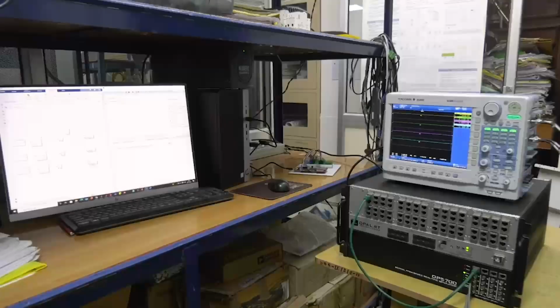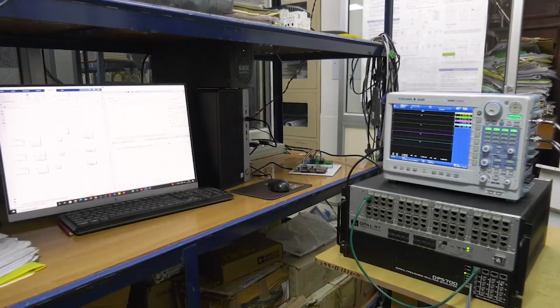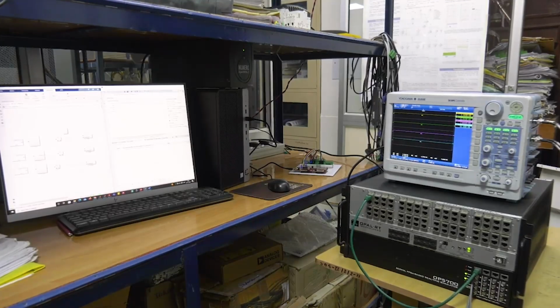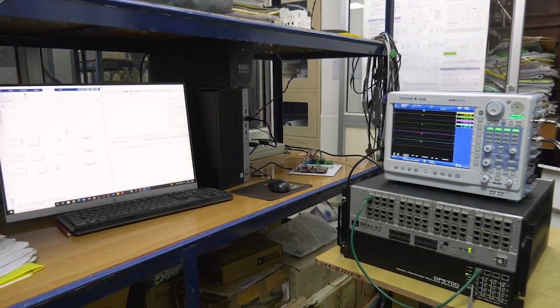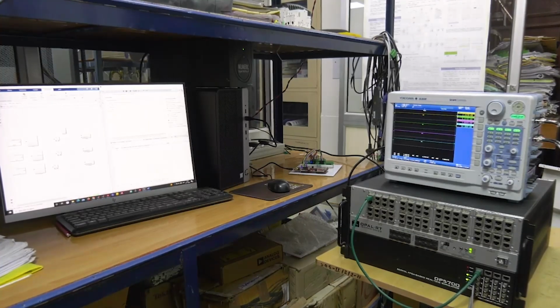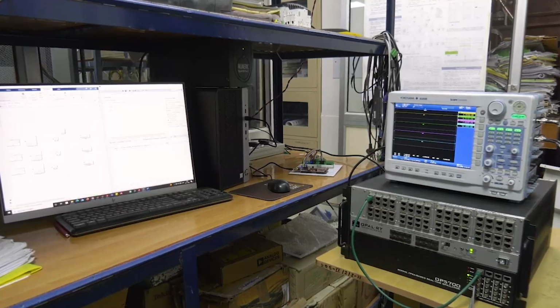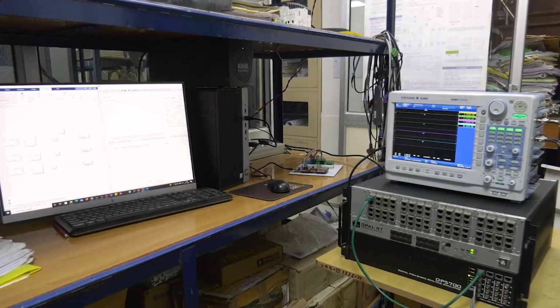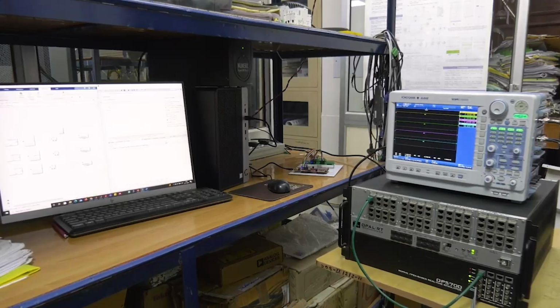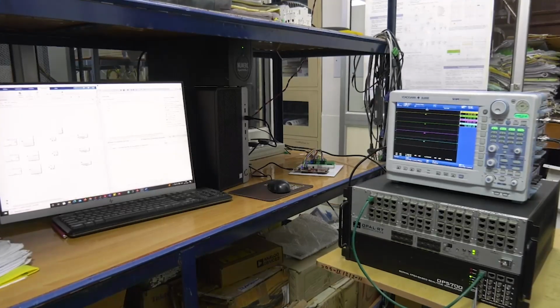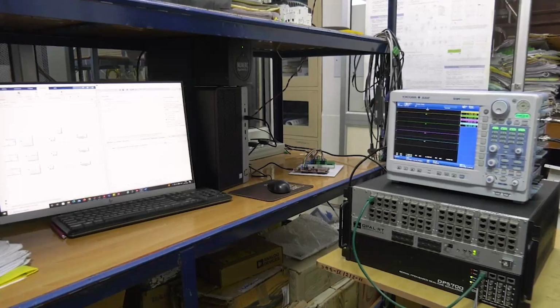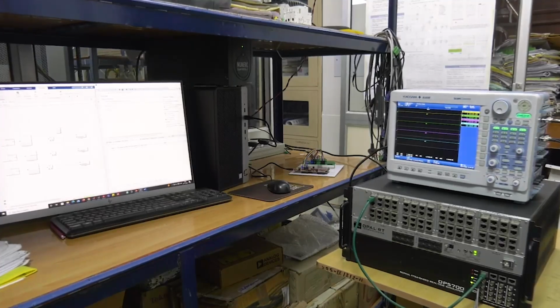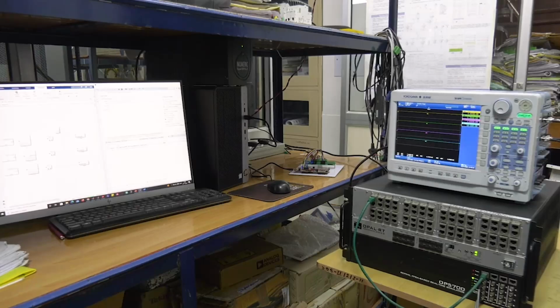Now, if you focus on discharging operation, the individual battery currents are presented in the DSO at the first 3 channels, SOC values in the next 3 channels, and power demand PD in the 7th channel respectively. Now, let us focus on the variations in load demand. To examine the control algorithm for load power variation, load power changes are applied to the batteries during discharging operation.